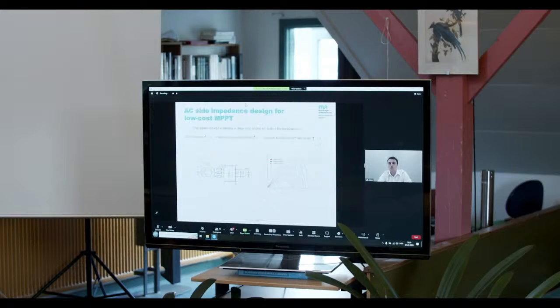The idea is to take advantage of the variable voltage drop in the AC side of the impedances, as you can see in the circuit below. This voltage drop is a function of the current that crosses the impedance. If the wind increases, the power generation increases, increasing the AC current amplitude, since the DC voltage is maintained constant in the right part, as you can see there.